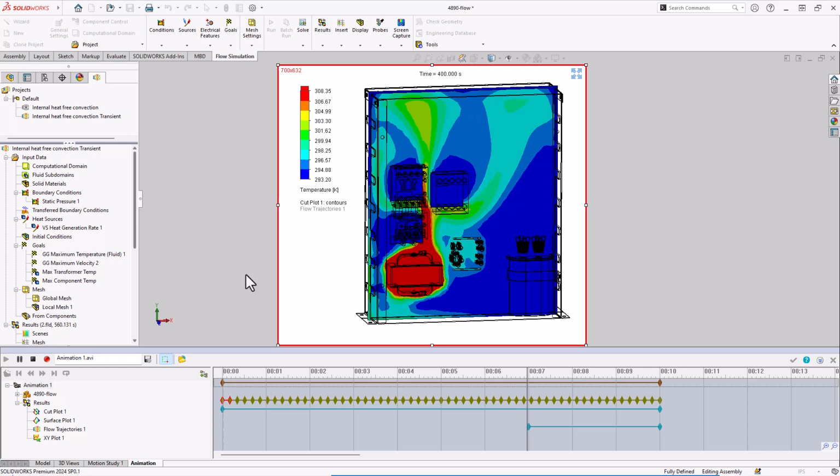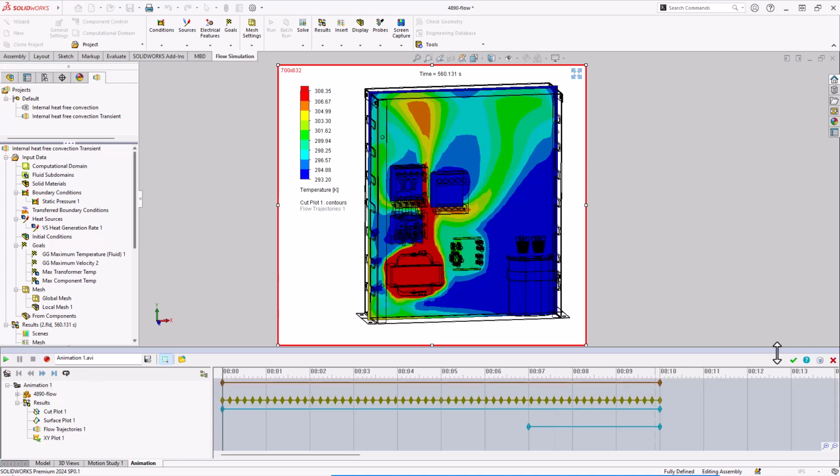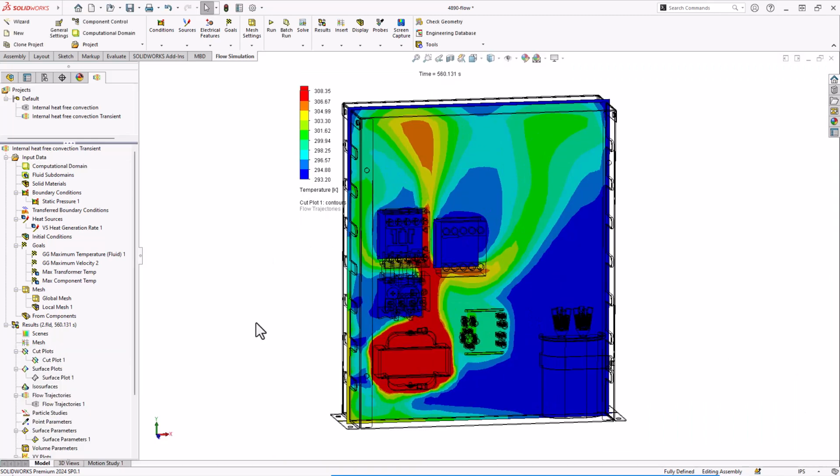And so now we turn on and solve the flow trajectories. This is going to add some time to generating these images, obviously, but it does a good job. If you're doing something, and you really want a nice smooth animation, you are going to have to really decrease the solving time step so that you get a lot of data and you can generate something really nice and smooth. All right, for the sake of time, I'm going to go ahead and stop this because I would like to take a look at reporting.